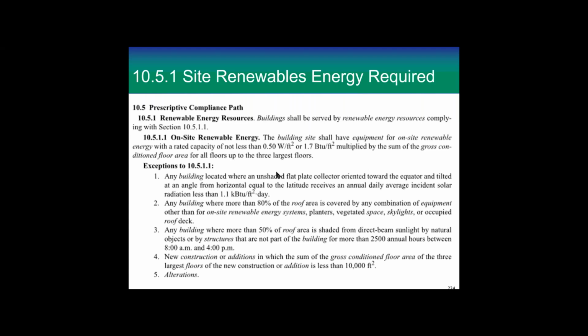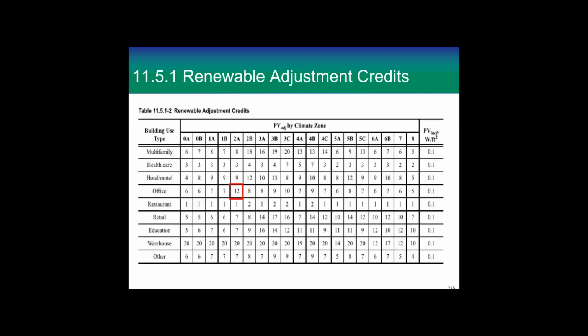So anyway, there's a big deal about each one of those points, no matter if you're doing HVAC or envelope or lighting, they are equal to the same amount of savings. And that's based on the calculation for the total building energy. And the total building energy has been reduced by the amount of this 0.5 watts a square foot. Now, if your actual building didn't get that reduction, then your points aren't the same value as the buildings that did get all of it. So you have to go back and do this adjustment.